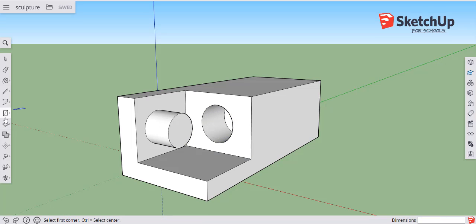Select the Rectangle tool again to draw a rectangle on a different face. Notice the red dot showing that you are on the edge. Pull the rectangle down to the lower edge showing a red dot. Pull this rectangle inward. All reference points are called inference points in SketchUp. They will be very helpful in making you both accurate and fast. The basic inference points are endpoints, on the edge, midpoints, and center points. There are more, but these are the most common.